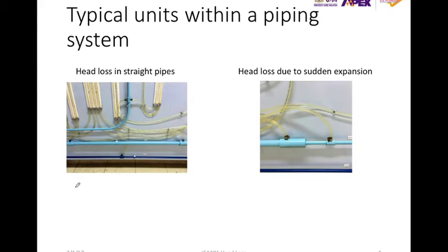To refer to what we discussed in the previous slide, we know that the hydraulic gradient is the head loss divided by the difference in length. So the difference in length is this. We can measure the head loss just by reading the difference in height in the piezometer. But there is also an equation that you can use to estimate head loss, given that you don't have these piezometers to measure the head loss.